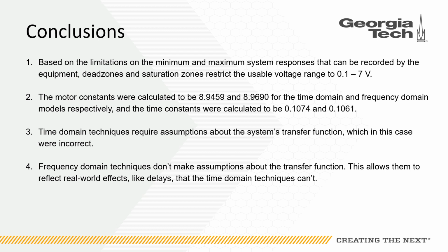These techniques only work for frequencies low enough that it is valid to assume the system is first order with a negligible time delay. Frequency domain techniques, on the other hand, make no assumptions about the transfer function and reflect the actual response of the system. As such, they are suitable for both cases 1 and 2,